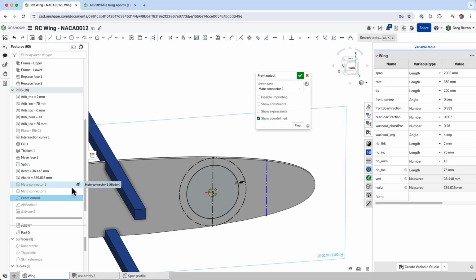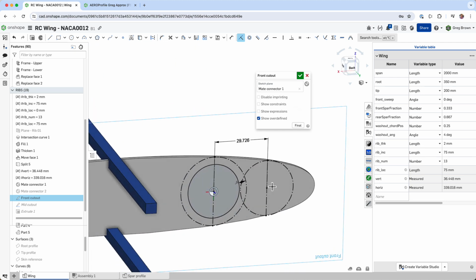I have created a measurement in there. All right. So now I'm going to place a construction circle somewhere on that line and coincident to the end point, and I'll do the same coincident constraint down here. So now this gives me a reference for creating another circle.